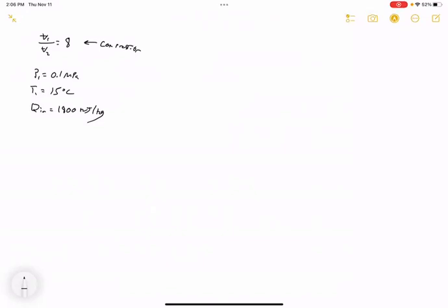How can we do this? Well, remember we spoke about these isentropic relations. Now we're going to get to see them in action. So, sorry about that. What we're going to do for T2 is use the first relation, which is T2 over T1 equals V1 over V2, which we're given here. It's the compression ratio, right? So V1 over V2 to the power of k minus 1, or well, okay, they use k, we'll use gamma, it doesn't really matter. Point is, it's the Cp over Cv.